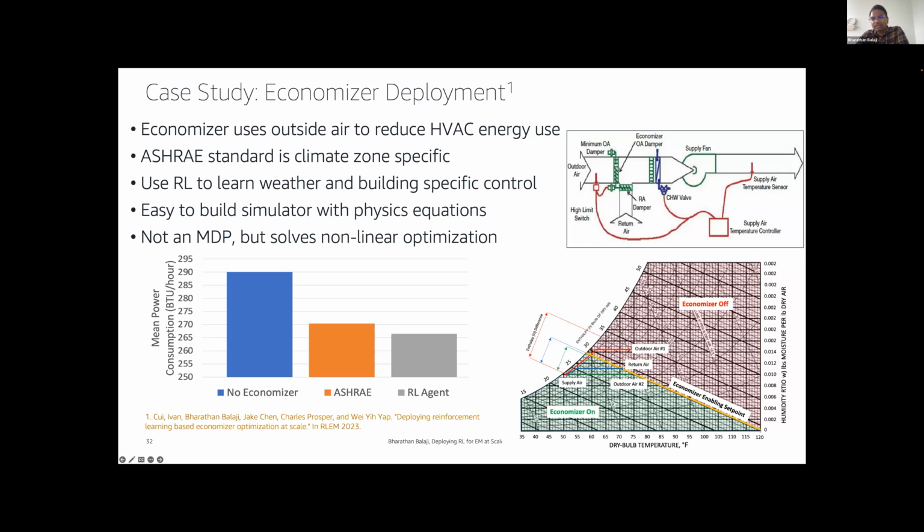those are not easy to predict. So whenever you have those kinds of elements in your simulation systems, which is the case in EnergyPlus, then it becomes really hard. But if you can make everything to the point where physics equations dictate the flow of what's going to happen, which is the case with this economizer system, then things get a lot more under control. So that kind of fork is what you should be careful about when you're formulating the problem. My opinion, at least. Yeah, it's a tricky one. Thanks for the answer. Okay, David has a question.